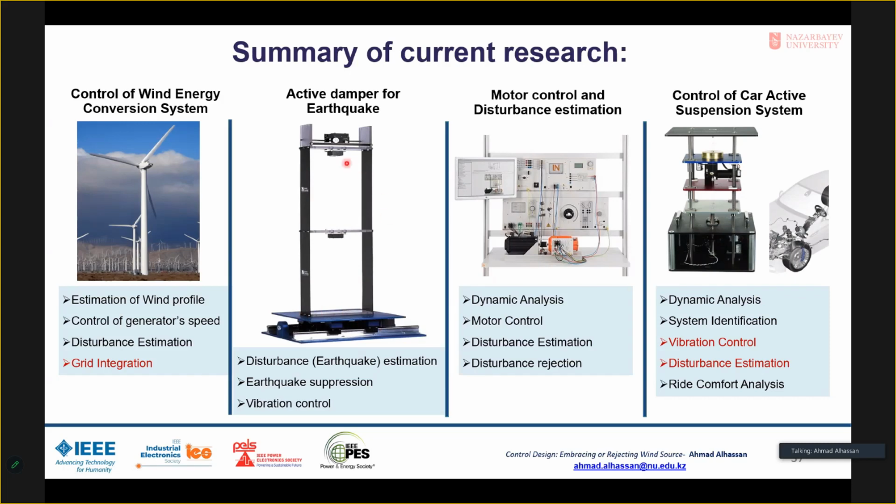This one will be vibrating, so now we have a counterbalance here. We make a control signal so that if this one is vibrating, this one will provide a tuned mass, which will be countering along this line. So this mass will be constantly moving along here to counter the induced vibrations from here.